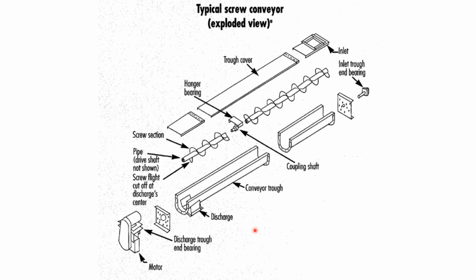Before going into the design of the screw conveyor, you should know its parts. The bottom, as you see, is called the conveyor trough. Here I have shown the U type. This can be round type, or a trapezium type, depending upon the flow of material, and the size is defined accordingly. It can also be a box type trough.